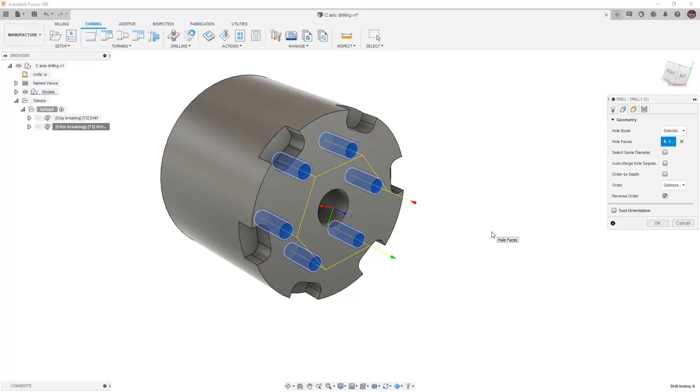Now, there are some situations where you would want to be aware of the method that we're doing here. If you don't have great repeatability in the spindle that you're using, you might want to drill and tap each hole position before moving to the next. Hopefully that's not an issue, but there are certain instances where you might want to consider drilling and tapping each position and then patterning that entire thing or redoing all of those operations.